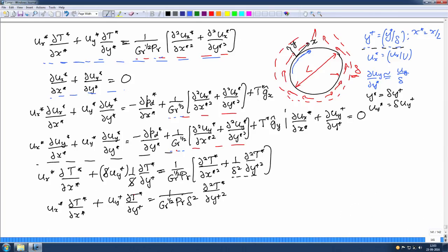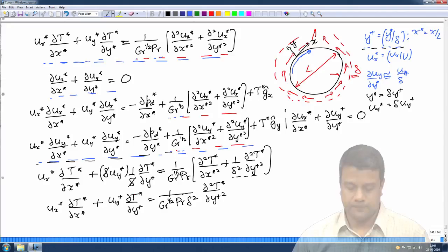Welcome to this, our final lecture on natural convection. In the previous class, we had defined the scaled equations for natural convection: the equation for the temperature field, the mass conservation, divergence of velocity is equal to 0, and the momentum conservation in both the x and y direction. These equations, the diffusion terms in both the temperature and the momentum equation, had a factor of 1 over Grashof number to the half in them.